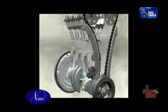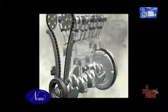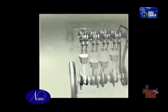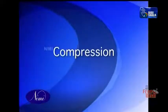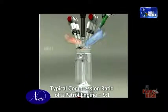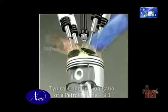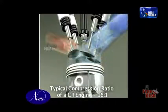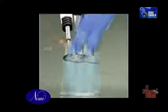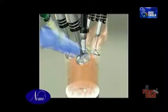Compared to the petrol engine, the CI engine is different in the following ways. Induction. During the induction stroke, only air is supplied and a full unthrottled charge is induced. Compression. The air is more compressed. The typical compression ratio of a petrol engine is 9:1. The ratio of a CI engine is about 16:1. This high compression results in the air being very hot at the end of the compression stroke.